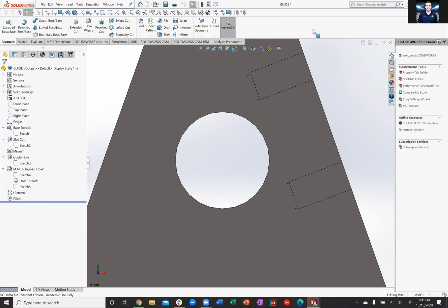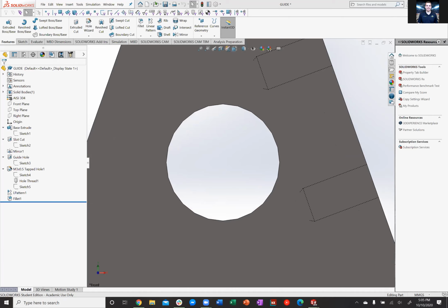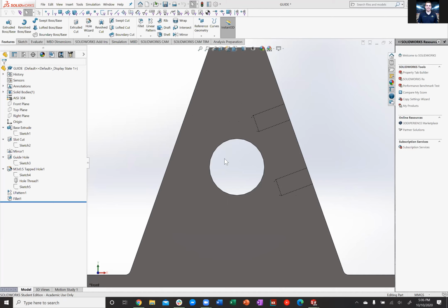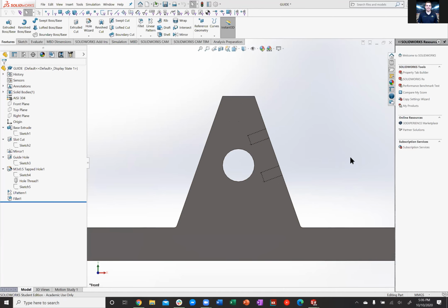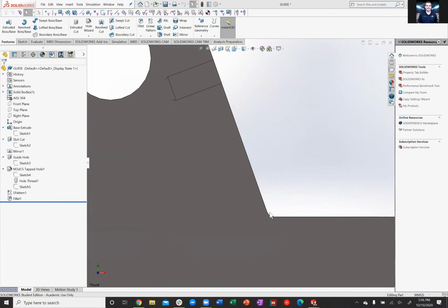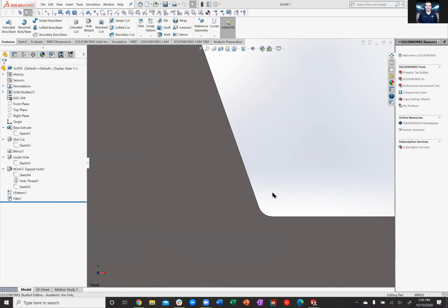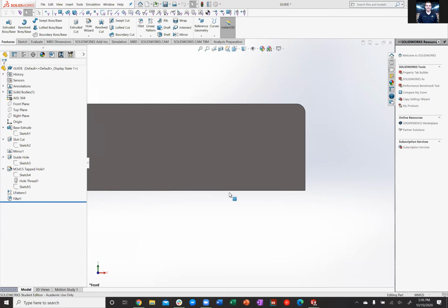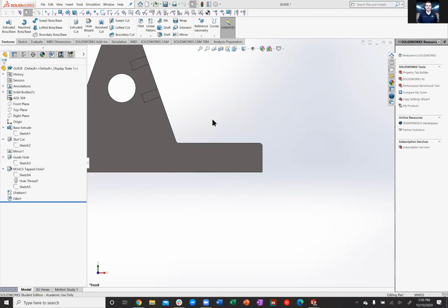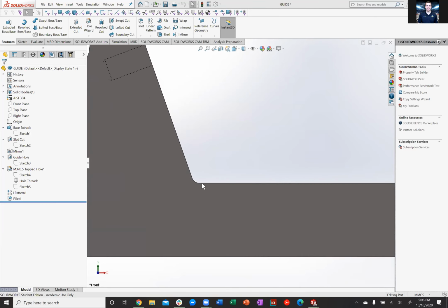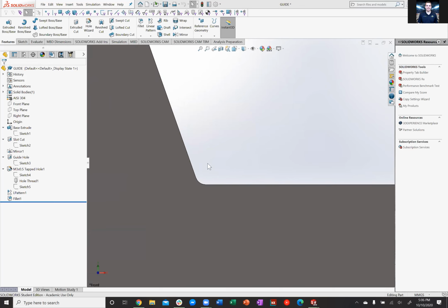There is such a thing as a square cutting hole for a mill, but there are limited options for square holes. So instead of doing a square hole, an end mill that cuts the material is round. So you want a radius on 90-degree corners that are inside. If it's outside, like over here, that's fine because the mill just comes all the way over here and then up. Over here, you wouldn't be able to get that sharp angle. So having that radius here would be good for manufacturing.